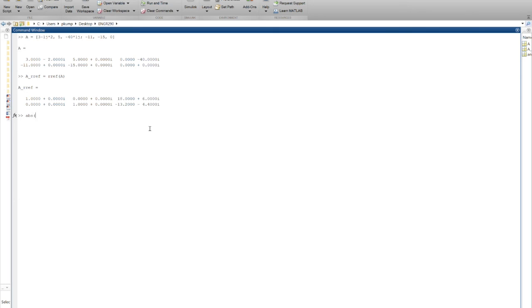Let's ask for the absolute value of row 1, column 3, that's this guy, that's V1. So I'm going to say row 1, column 3, ABS. All right, so this thing here has a magnitude of 18.9737, and I'm going to ask for the phase of that thing, and I'm going to ask for degrees, like that.